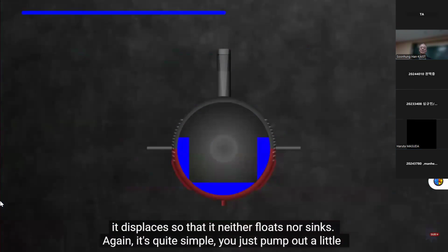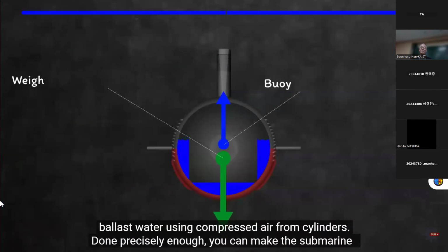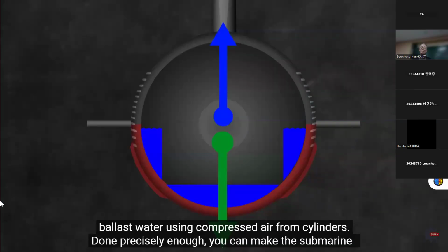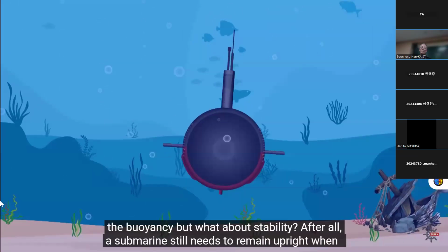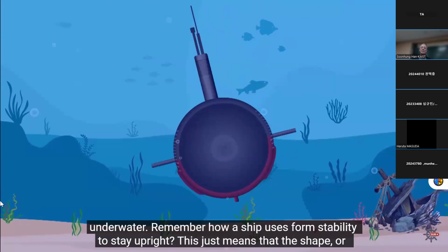Again, it's quite simple, you just pump out a little ballast water using compressed air from cylinders. Done precisely enough, you can make the submarine weigh the exact same as the water it displaces, making it neutrally buoyant. So, that deals with the buoyancy, but what about stability? After all, a submarine still needs to remain upright when underwater.